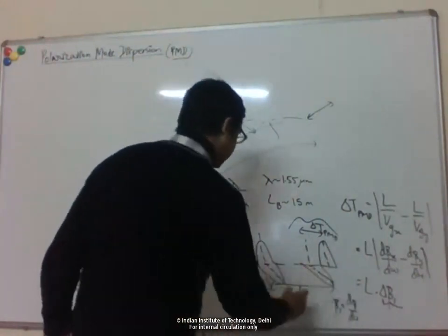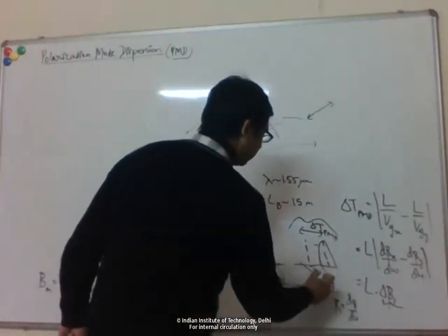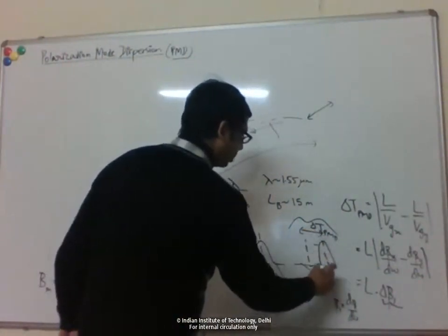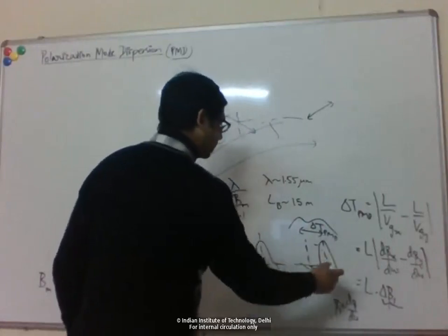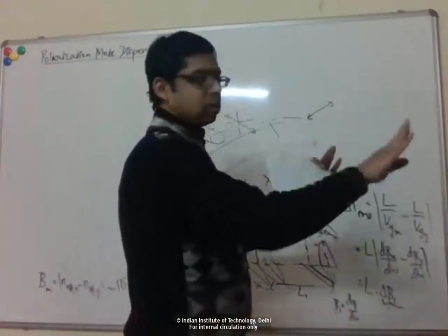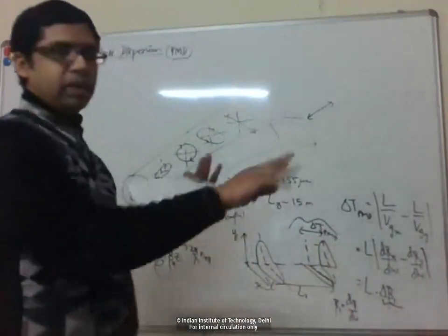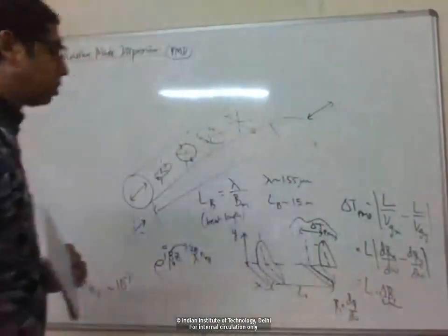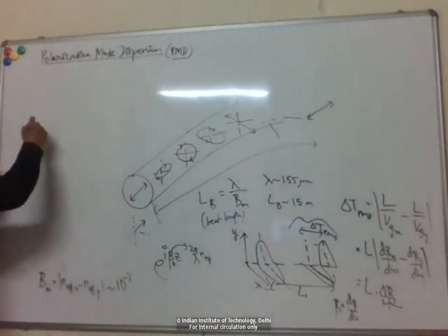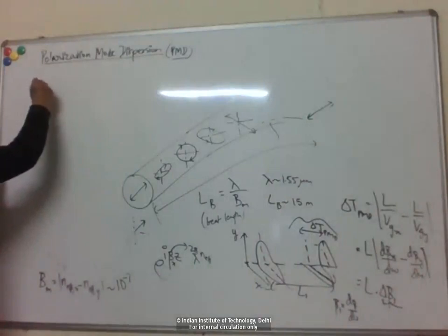Then the next section happens where maybe this is traveling a little bit faster, this is traveling a little bit slower. So maybe it becomes like that. And then the next section comes, right? So basically you have these pulses sort of going backwards and forwards, and then you integrate the effect over the entire length, right? So you characterize what is known as RMS delay.